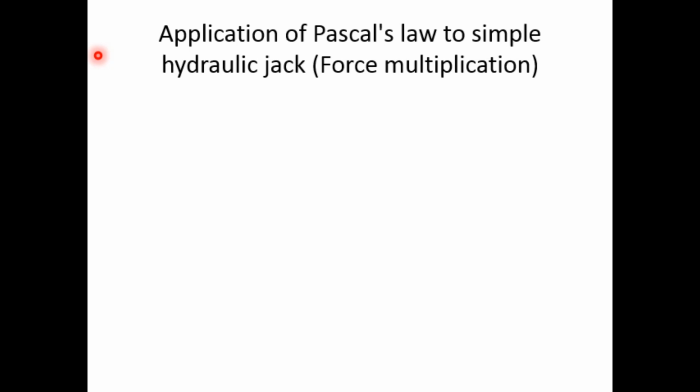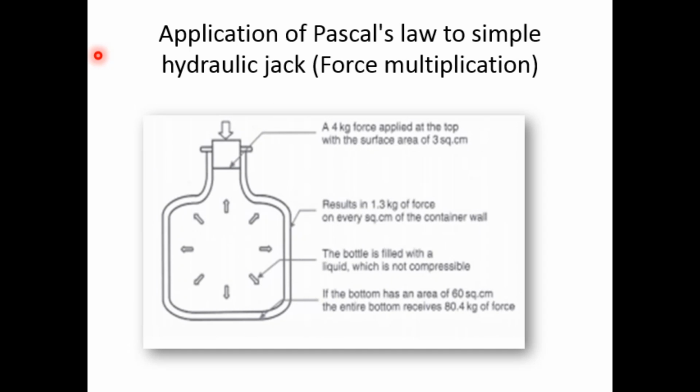So theoretically I have told you the concept of force multiplication. Now I'll tell you, by showing an example of a hydraulic jack, how the force is getting multiplied. Just look at this particular sketch. Here you can find there is again a container placed. In this container you have a knob or a moving piston. This moving piston is able to move down to compress the fluid present over here. At the same time, it has to take care that no fluid will escape out from here, so it should be perfectly sealed by using seals.